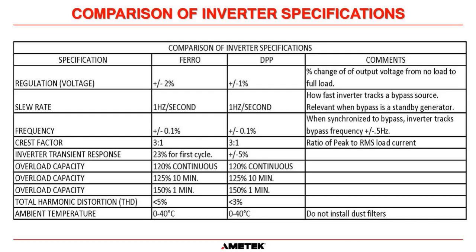Next thing we see is overload capacity. And this is something a lot of the commercial UPSs won't tolerate. A lot of them won't even go to full load. Our spec here for industry, though, is 120% continuous, 125% for 10 minutes, and 150% for 1 minute. So you've got quite a bit of overload capability in there, and you have to design that in. That means more transistors or bigger transistors for the inverter bridge to supply that. Your cabling, your transformers, everything has to be oversized, but that's what they need in industry.